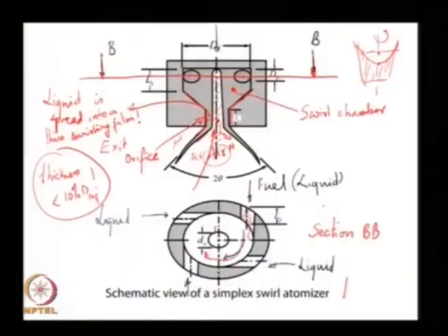As soon as the liquid exits from the other side, because the swirl creates an additional centrifugal force that is now unbalanced from the wall reaction, it is going to further expand outwards, and this further expansion outwards does two things. One, it increases the interfacial area between the air and the liquid even more, and two, it slows down the swirl of the liquid. It is just now the reverse of the ice skater problem.